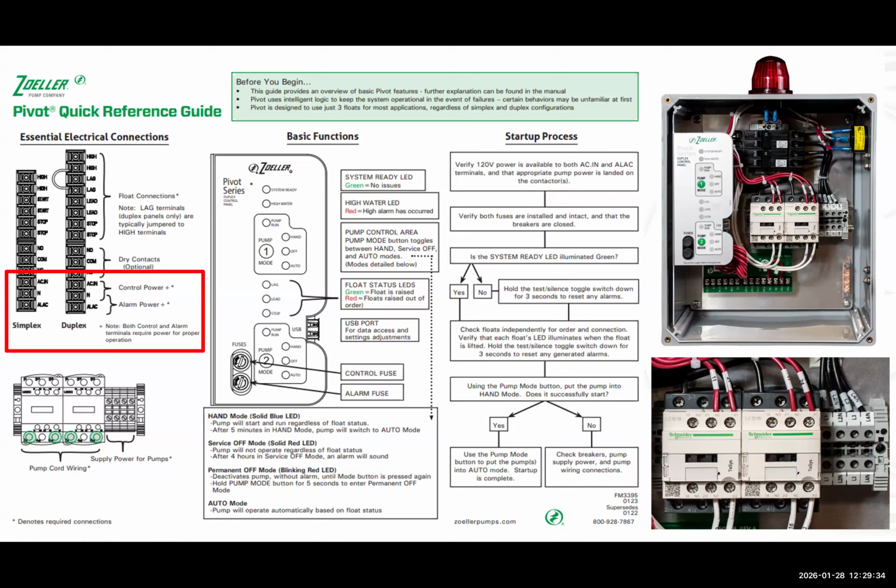It will either appear dead or all the lights are going to come on and it's not going to be responsive. And so, we get a lot of calls in product support because people describe the behavior that it's exhibiting. And the first question that the tech will ask is, did you bring in power to both the control and alarm power, which is ACIN is how it's marked, and then alarm AC, ALAC. And that's typically the issue.